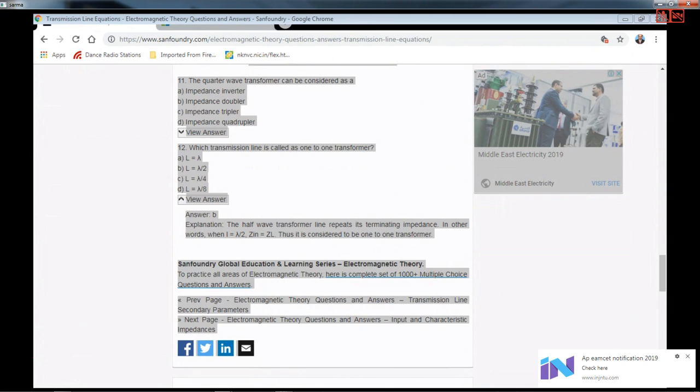Why does it come like that? Why is there ambiguity? It is because the VSWR is dependent on mod gamma. It's not on the actual gamma value, it is dependent on mod gamma. So mod gamma for the -1 or +1 condition is the same. Thereby, it gives you the same VSWR value, and the ambiguity is between short circuit and open circuit.